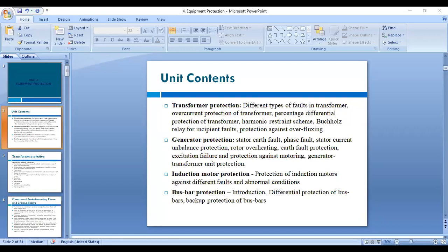Why is the current transformer used? We have to measure the value of current through those transmission lines. That's why we are using this current transformer, because current transformers can step down that current to a measurable value. So now this current transformer is connected in which, star or delta?